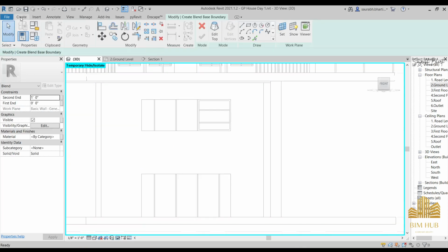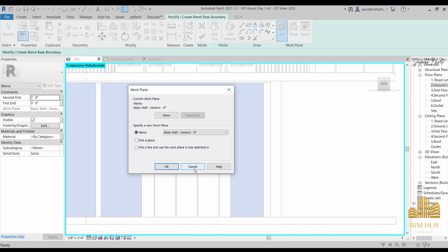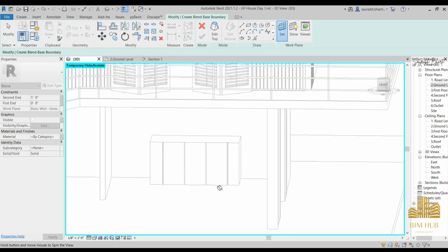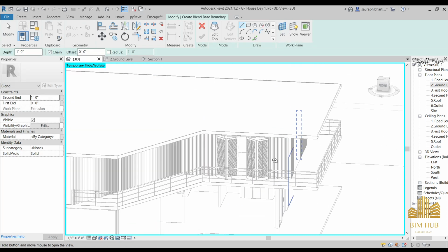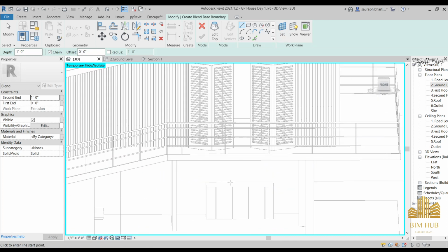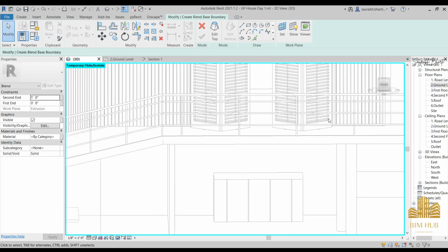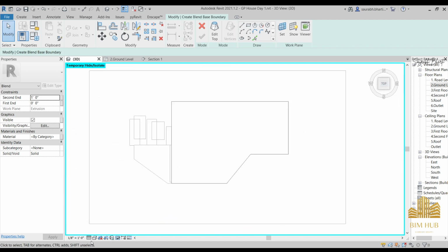Go to the extrusion once again. Okay, extrusion, set a plane and pick a plane, and here you can just select this plane, and how will we make in that plane? We have to make a rectangle at that plane. So what we can do is we can go to the top view, but it is not visible in the top view.